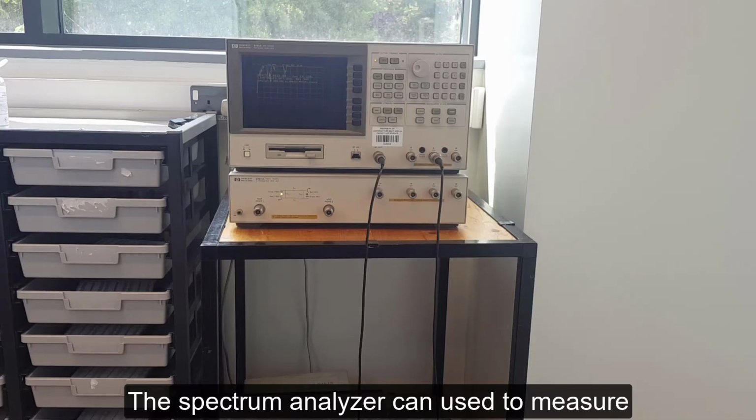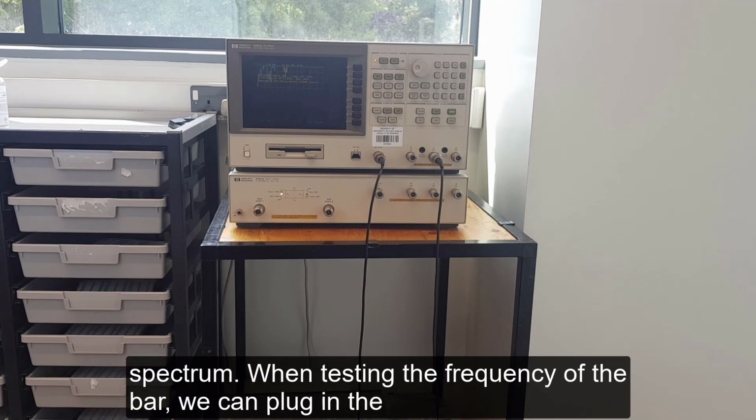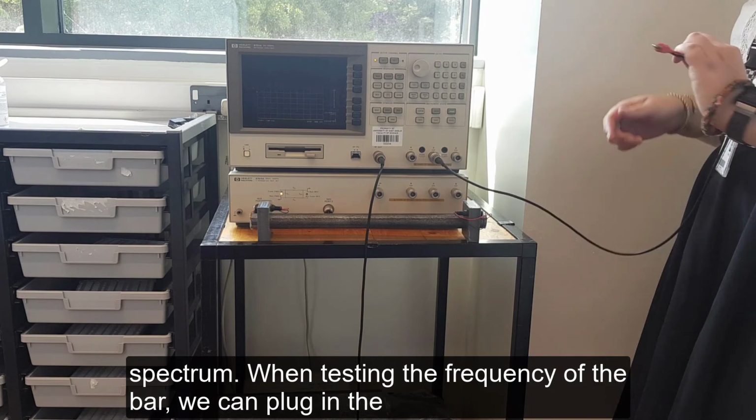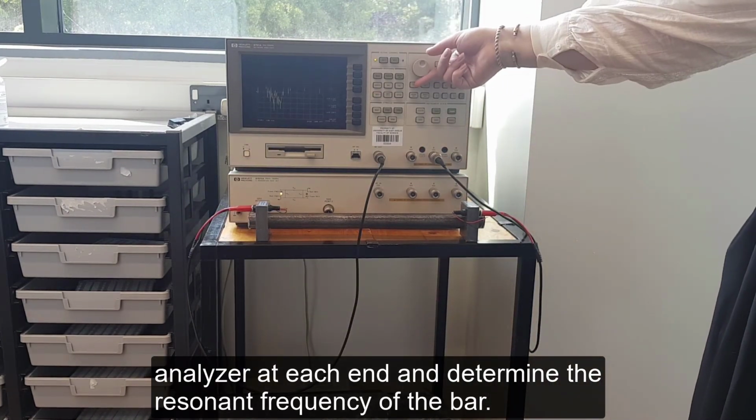The spectrum analyzer can be used to measure the magnitudes of a signal for a set of frequencies within a given spectrum. When testing the frequency of the bar, we can plug in the analyzer at each end and determine the resonant frequency of the bar.